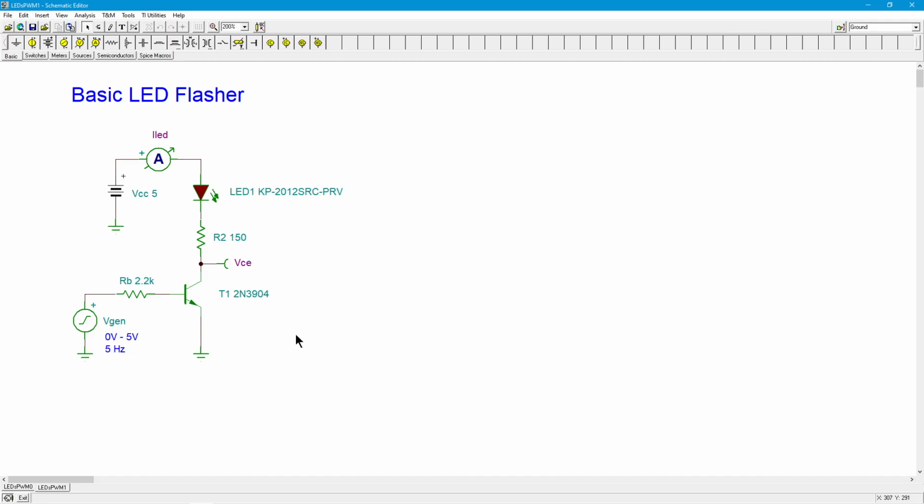So you're probably looking at low to mid 2 volts taken up, which means probably somewhere in the vicinity of, depending, 2.5 to 3 volts available across R2 over here. This is the collector resistor. So we could just use Ohm's law, take that potential, if it was 3 volts divided by 150 ohms, you got 20 milliamps.